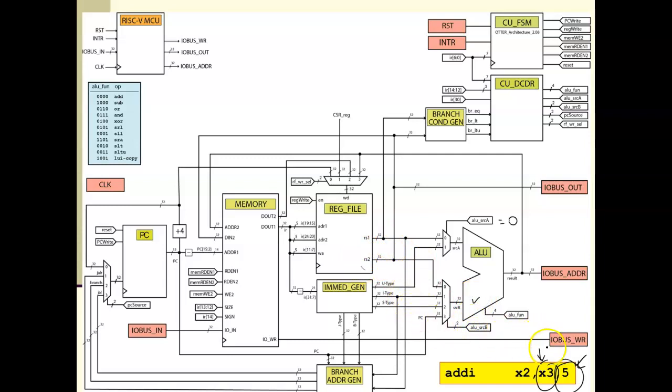And so what we're going to do is look at the instruction. We're going to see it's an I-type instruction, and that's the I-type value I want to put in there. So source B is, of course, 0, 1. And guess what? For the last problem, I forgot to fill in the ALU operation. They're both adds. I know it's a 0, 0, 0, 0 because I look at this table up here and I can put in the select bits.